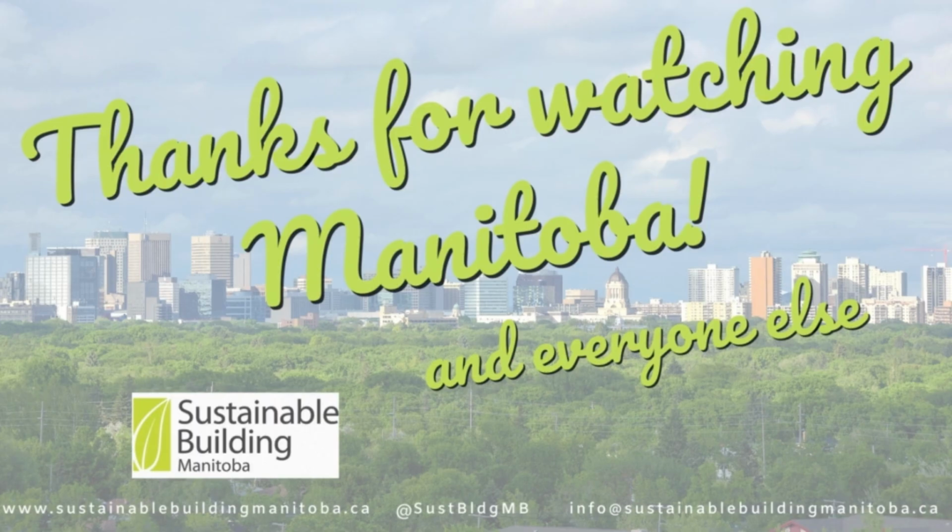But as we get further to the north, we start running into discontinuous permafrost. And we tend to see the rock temperatures getting cooler and cooler down to a certain depth. So it's very important that the investigation would identify those things ahead of time so that you're not getting into a situation where it's just not going to work.